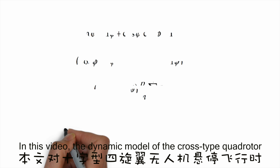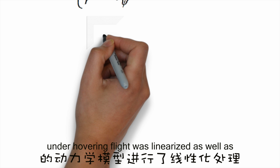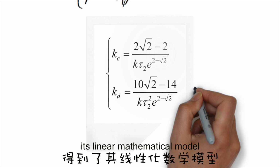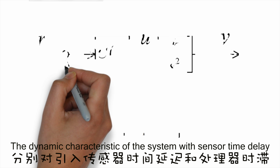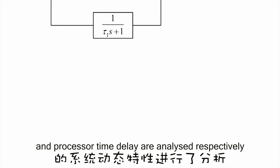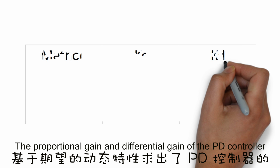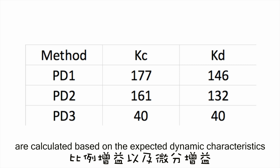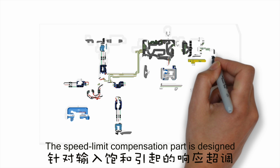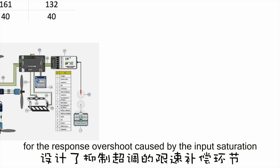In this video, the dynamic model of the cross-type quadrotor under hovering flight was linearized, as well as its linear mathematical model. The dynamic characteristics of the system with sensor time delay and processor time delay are analyzed, respectively. The proportional gain and differential gain of the PD controller are calculated based on the expected dynamic characteristics. The speed limit compensation part is designed for the response overshoot caused by the input saturation.